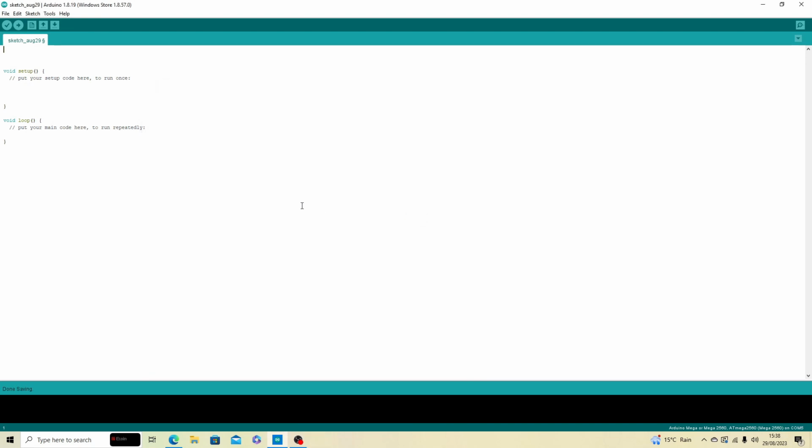I'll use the sprintf function, and that allows printing and formatting. So I can pass a value in to be printed and converted, and then convert that to hex. I could use an integer, but an integer only holds 65,000 and 20 address lines is 1,000,000, so I'll need to use a long instead of an int.